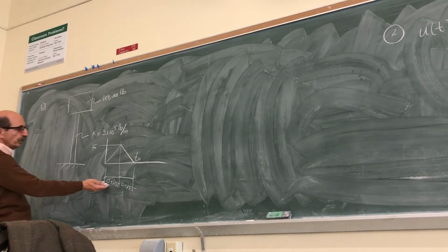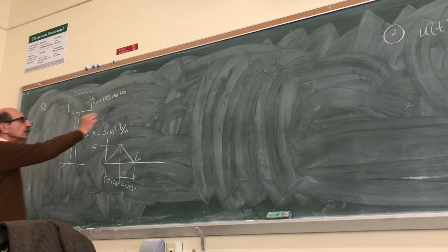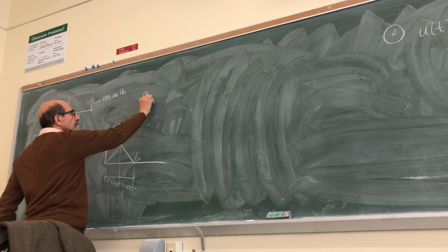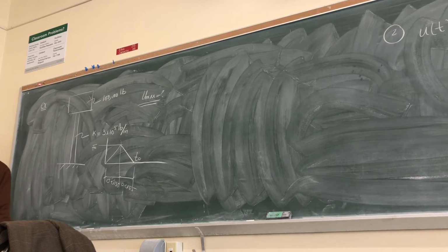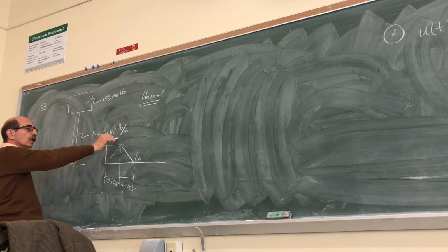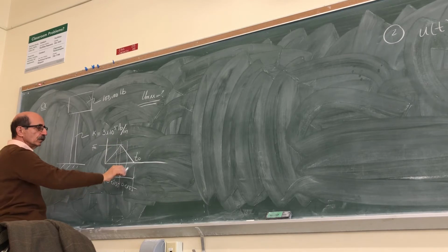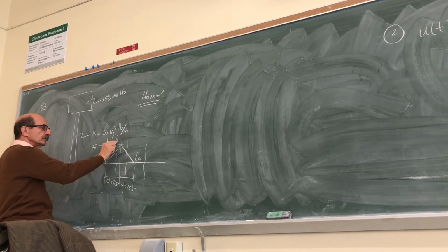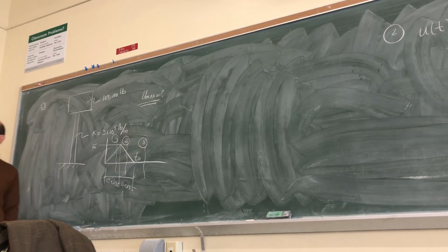So it's about 0.016 second, 16 thousandths of a second, right? We want to find out what is the maximum displacement of this water tower. We need to find out because we don't know whether the maximum force displacement would happen while we're here, or here, or here. We have 3 regions for which we need to evaluate this Duhamel integral.